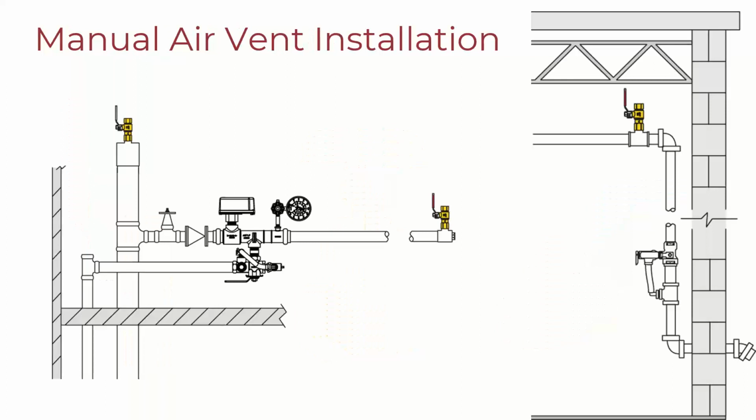It could be as simple as, number one, a manual valve, 1/2 inch and larger. These can be located at the top of the supply pipe, the standpipe. It could be located at the end of branch lines. It could be located on the top side if you have a single-story building, as long as it's near and fed from a high point in the system.